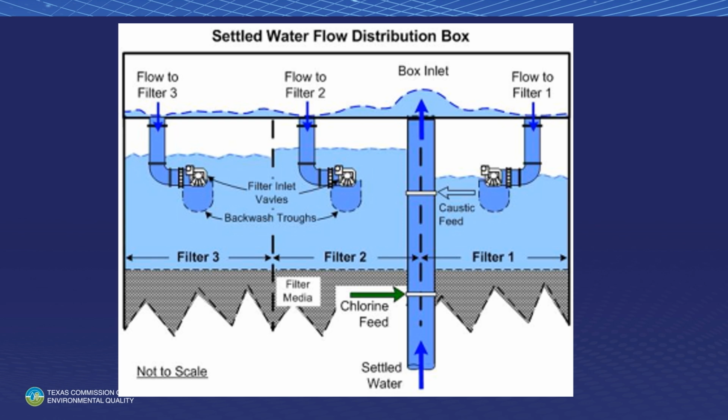It was because there was inadequate mixing in that pipe because of the laminar flow. And sure enough, when we got to the bottom of the pipe, filter 3 had a pretty good chlorine residual. I can't remember what it was, but it was satisfactory. Filter number 2 had one that was okay. It wasn't too bad. Filter 3 had no chlorine residual on the bottom at all.